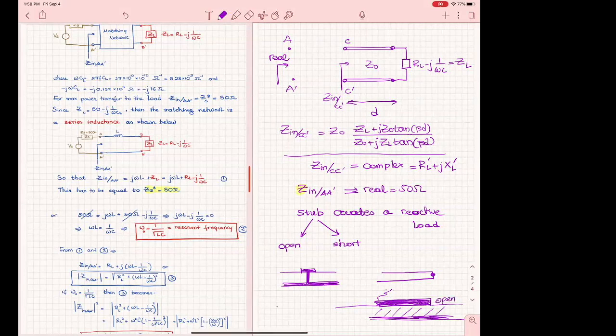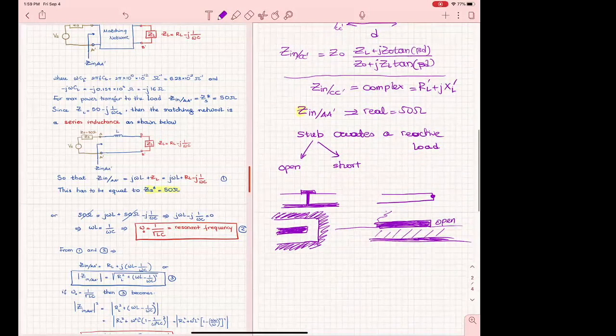Now, if I use a coplanar waveguide, which looks something like that, and at some point we'll talk about this, I bring the ground around it. This is my center line, and around it is the ground. The white area is open, like the surface of the wafer. Then a short here is better.